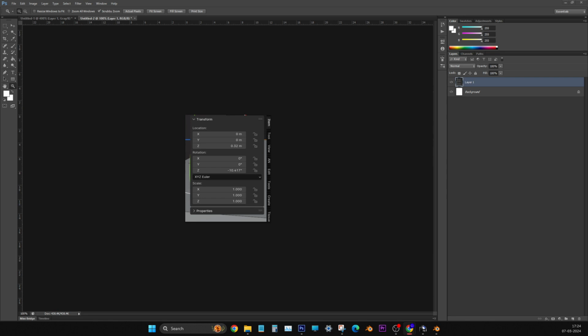Now go to the backside, bottom backside of this cube. The last two vertices are there, no? Alt A, deselect. Last two vertices are there. You just go there. That one. Now hold Shift and then select the next vertex.